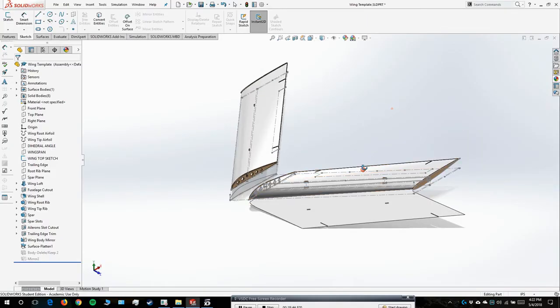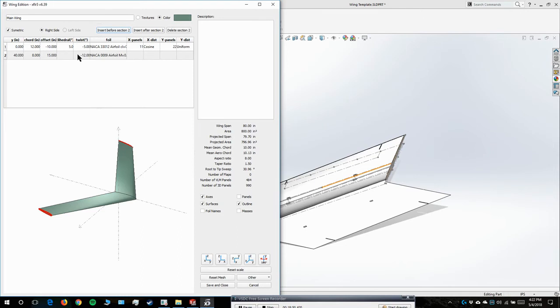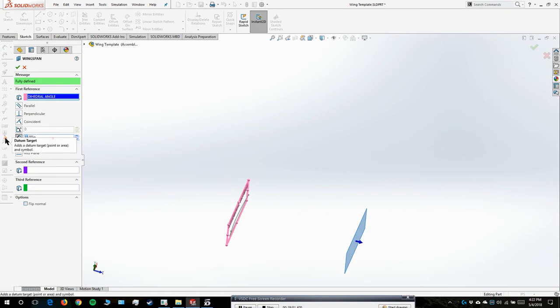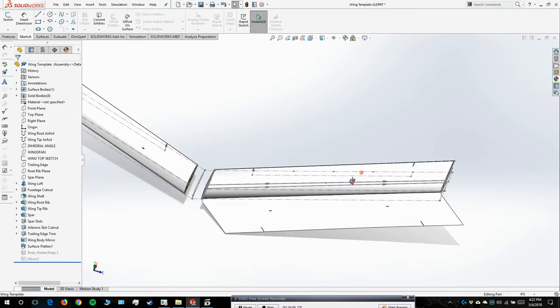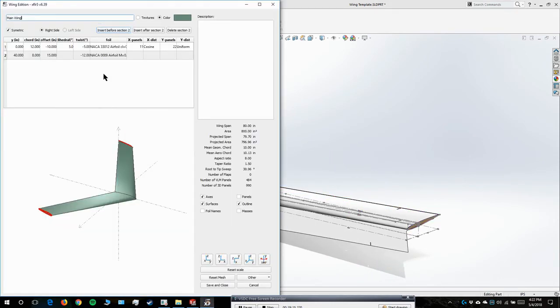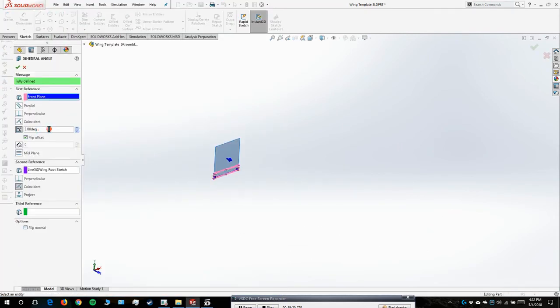As you can see, the wing tip has been updated, but some of the dimensions are not correct. So you have a 40-inch wingspan on each wing. So you will update the wingspan parameter to 40. Just like that. And your dihedral angle is 5. So change the dihedral angle to 5 degrees. OK.